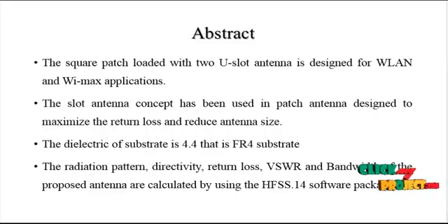The third method, the dimensionally invariant resonant frequency method, which optimally combines the features of the previous two, is developed here. It is shown to have better bandwidth performance with minimal or no probe location optimization, and hence is superior to the other two.